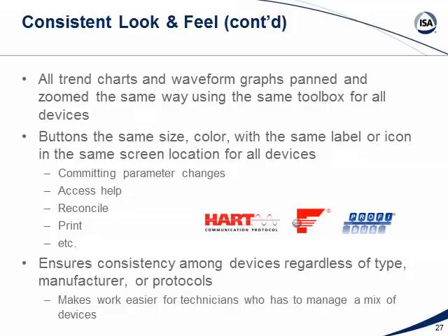And whether it's a temperature, pressure, or valve positioner from companies A, B, and C, it's going to feel like you're working with a common set of products, irrespective of who built those particular products and irrespective of the communication network that product might sit on. So whether you're interacting with a HART device, PROFIBUS device, Foundation fieldbus device, now I hope you're interacting with Foundation fieldbus because that's who I work for, but nevertheless, while you're working with all of them, it doesn't matter, because they're all going to have that same experience in working with those particular products.